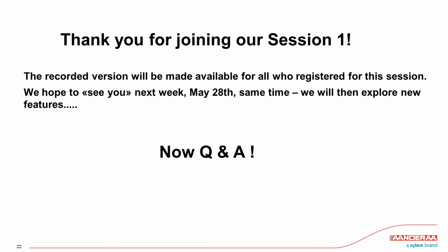Great. Another one here. Does the calibration of the sensor need any qualification? And how long does the validity of the calibration last? That's a good question without any 100% answer. We've had sensors out there which have been calibrated once and have been working for more than 20 years. We've had other sensors which have seen beatings which require recalibration way more often. Some cases more often than we want to. It depends on shock loading of the sensor. It has to do with installation of the sensor. So it's a very good, relevant question, and I'm afraid I don't have the answer to it.